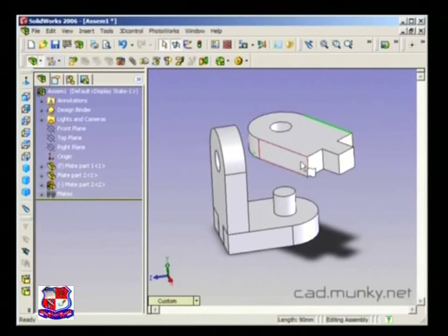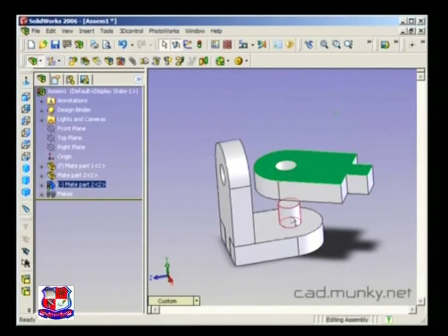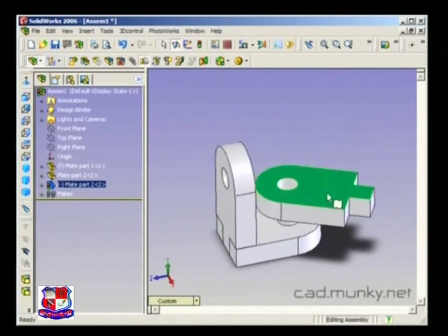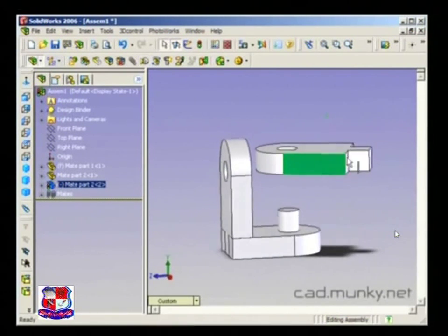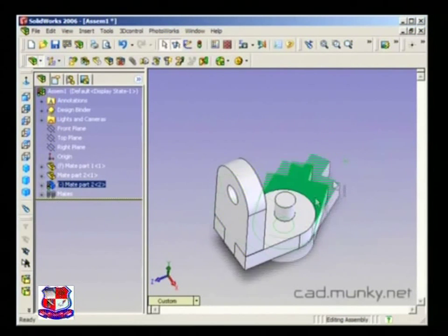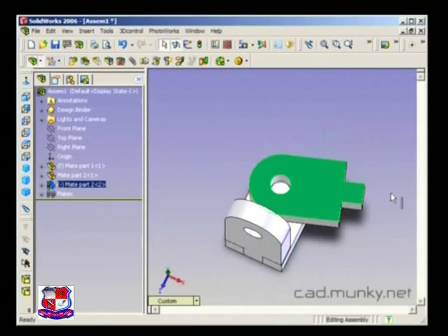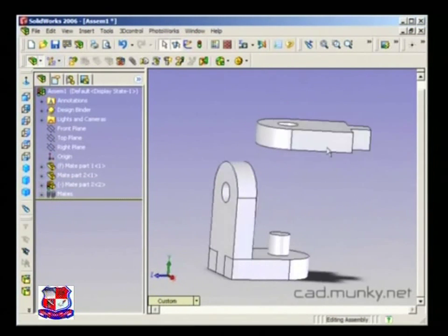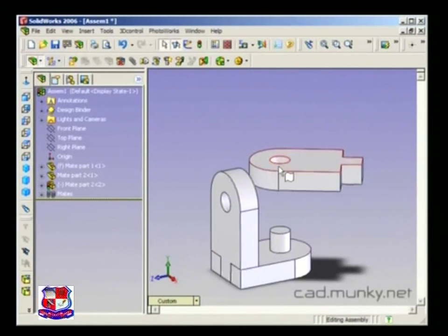So now you can see that these inside and outside faces are lined up in a way that the pieces have to be right on top of each other in this way, and the freely moving piece that's not fixed in place can be rotated like this. I've also got this motion up and down because it's not taking into account the fact that the peg stops here. It's extending that cylindrical surface infinitely up and down. Same with the inside surface here.